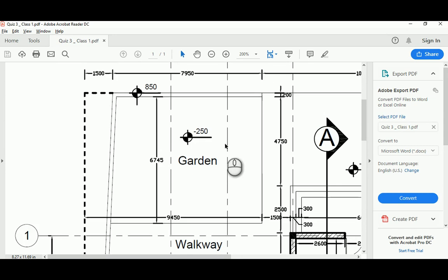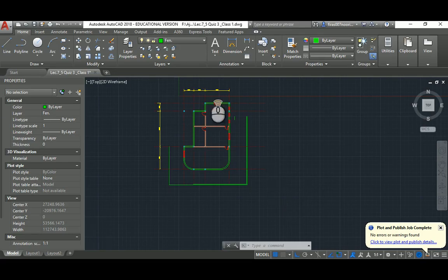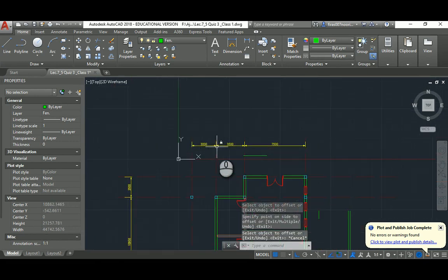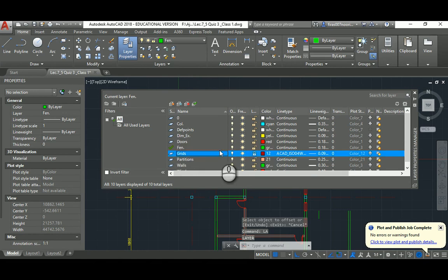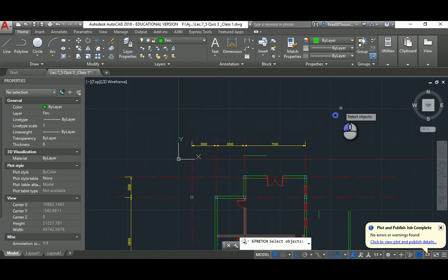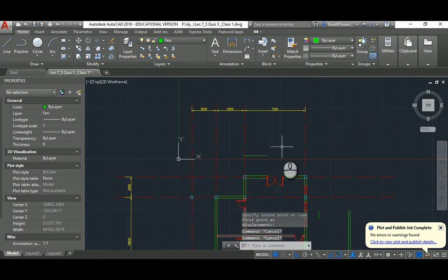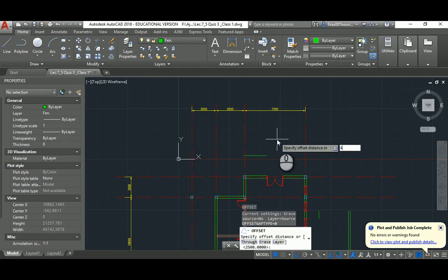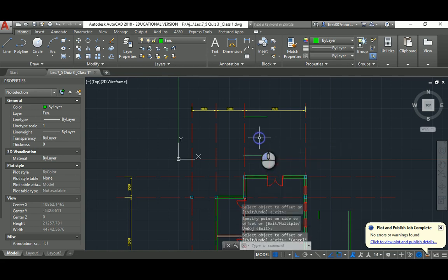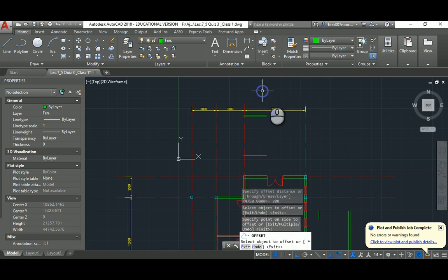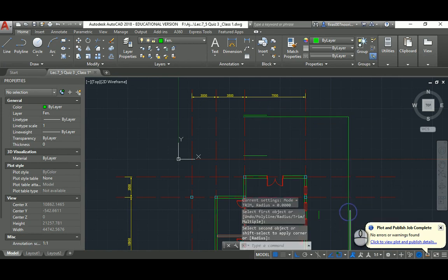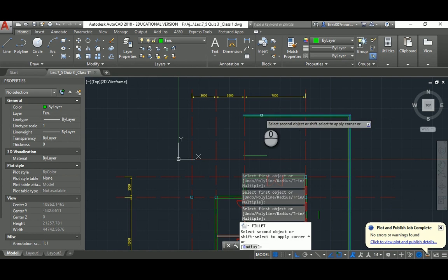Now, wow, that's annoying. Again, we should go 150, no, 250. Beautiful. Here, offset 250, like here. So I noticed that we need to go more, and in this case we have to activate the axis or the grid, unlock it, and probably a little bit of a stretch in here like that. Better. So again, it's 2500, 4750, again 4750, of course a 200. I think I need another stretch in here. Now fillet this guy with this guy, and then this guy with this guy. Now I will close the outside.